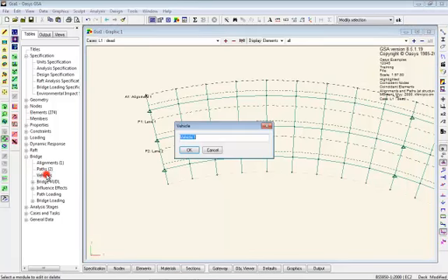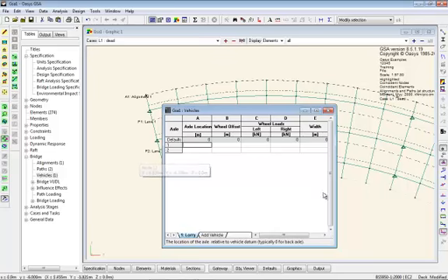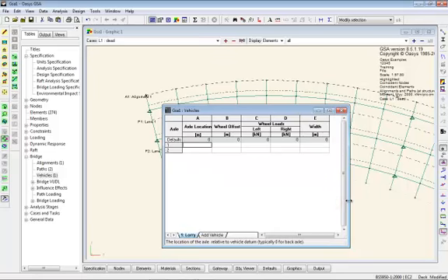For the vehicles, I am going to create a lorry. For the lorry, you specify axle loads and the location of where the wheels go. So, back axle, 0 meters offset from the centre line, the wheel load on each side, and width, which is used for lane checking, but I'm just going to take it from the wheel size.